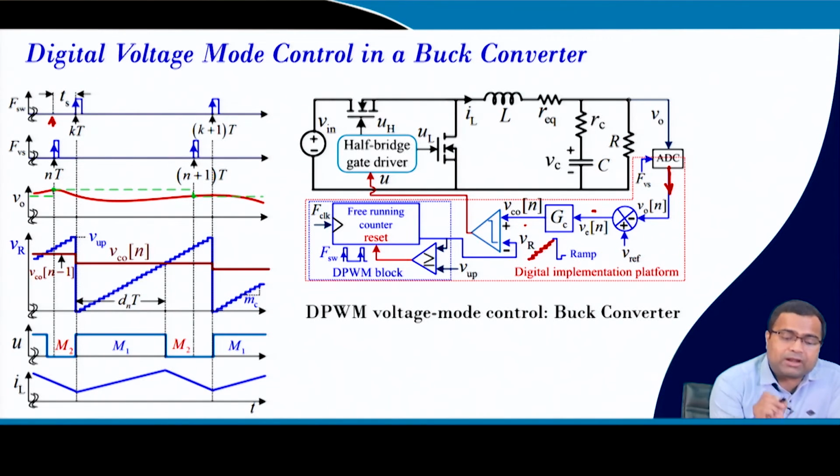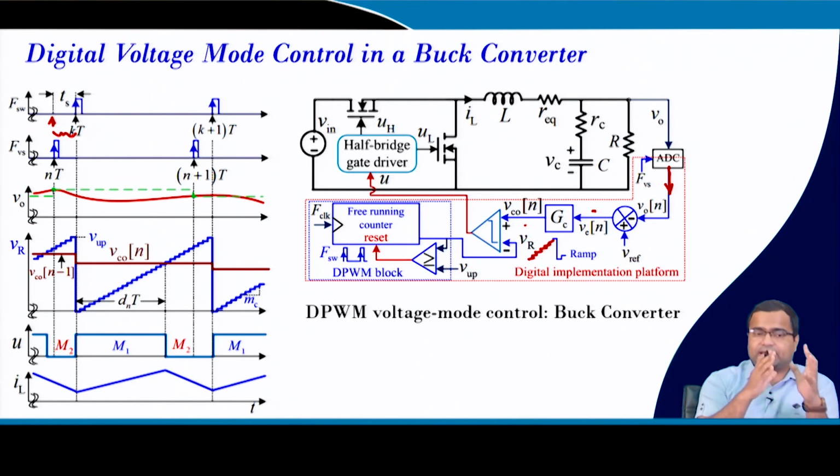And if we want to draw the waveform, we have discussed that generally we need to send the sampling command much earlier, because it will take some time to convert the continuous time signal. It will include the ADC conversion time and controller computation time, and this time can be pretty large. In fact, it can be comparable with the switching period, or in some cases even higher, because at high frequency we need to reduce the computational burden.